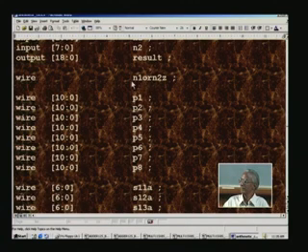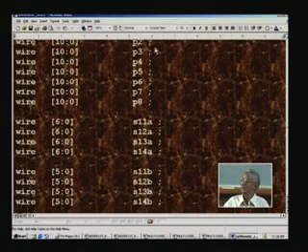Here we check whether each of the two numbers n1 and n2 is 0 or not, and we have a separate flag for that, which is declared here. There are also the many partial products we have seen earlier, which are 11 bits, and we need to declare them as wires, since they are all evaluated as assign statements.